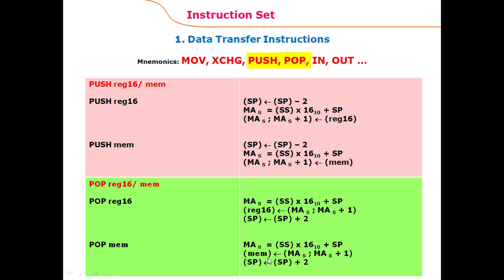The address calculation for this memory location is not mentioned here, but it is similar to the calculation used in other addressing modes, where the data segment content is left shifted by one hexadecimal digit, and the offset address provided here is added to that 20-bit starting address of the data segment, and bytes are then written to that memory location and the next higher memory location.